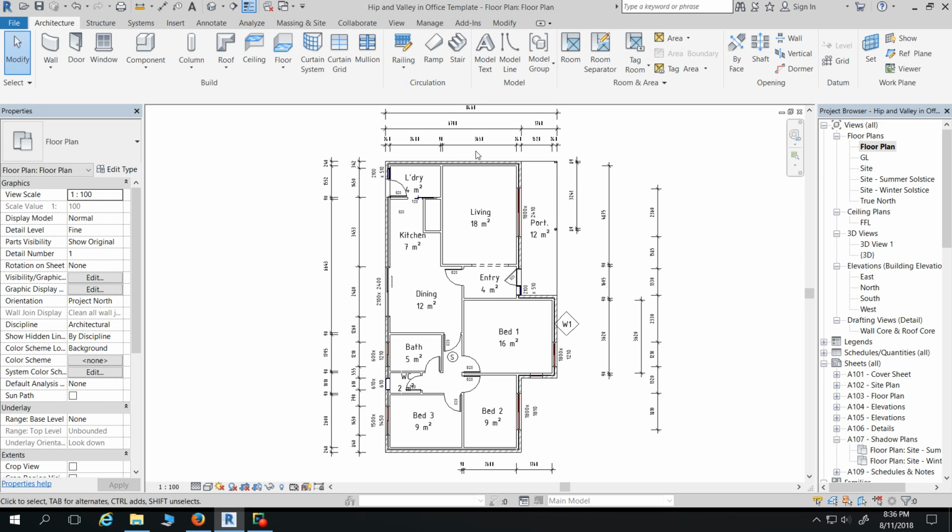Yep. And then just do your right left thing and grab these 3 ones. Or grab them all and then hold shift down and hit that one. Now you can undefine slopes. Yep. And then that one you just want to say maybe 5 degrees. So click on that one, the sort of triangle. 5 degrees, enter. Yep, cool. Maybe minus 500 off the ceiling level. So base offset, just go minus 500.